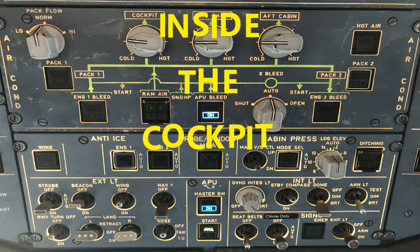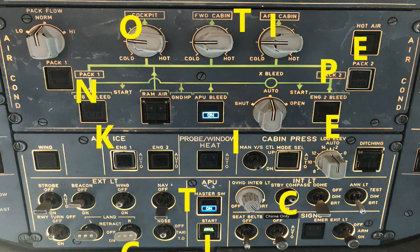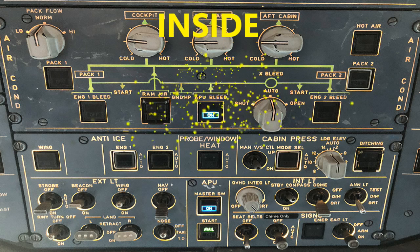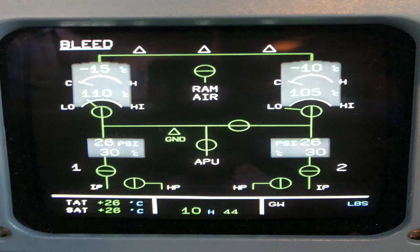Now, for your engine 1 and 2 bleed, when you have it on, the bleed valve is open, but it could also be closed. It just depends on what the selection is for the cross bleed selector, and also for the APU bleed switch. All right, and then of course a fault light is going to come on in amber on that push button switch, associated with the Ecam caution. Okay, that's the Ecam bleed page, of course, along with the master caution light, and there's also an aural warning. So there's going to be an auditory sound when there's a fault.